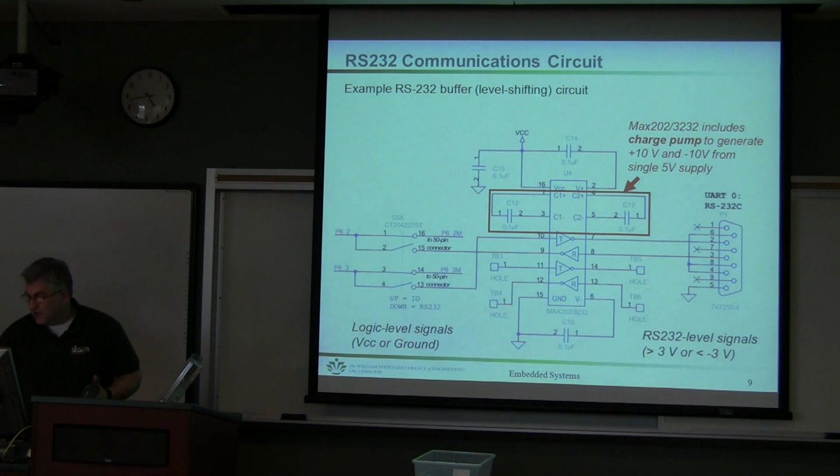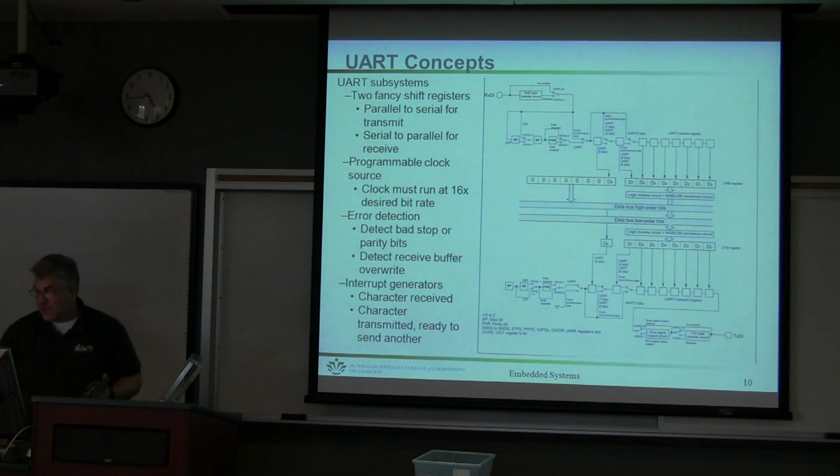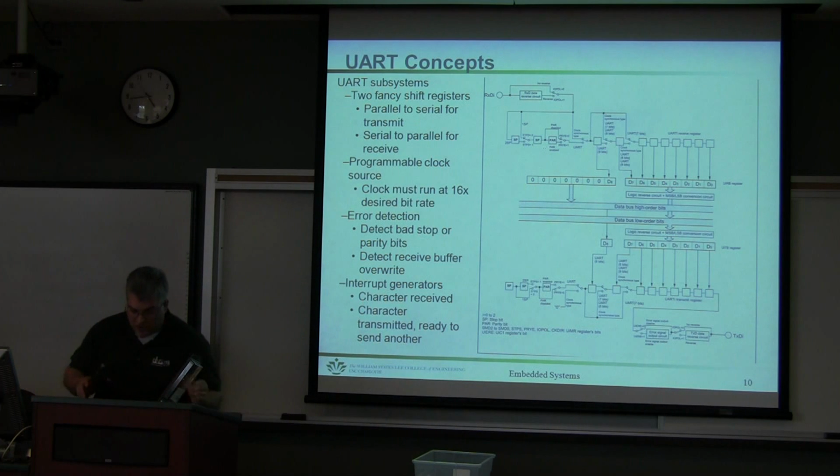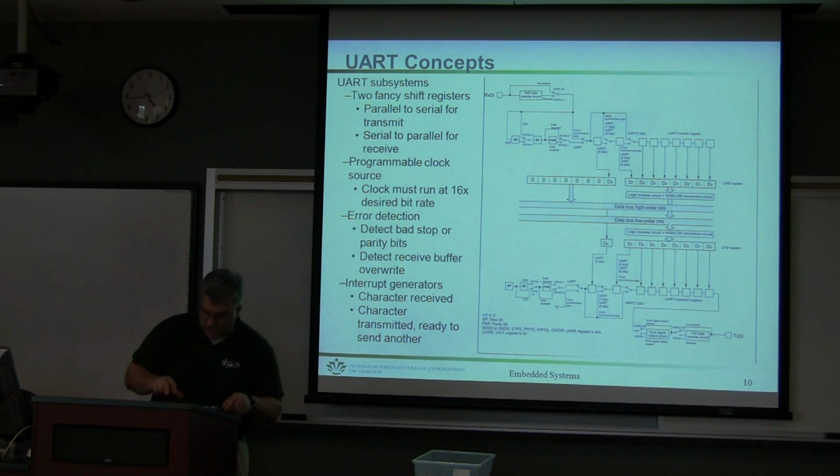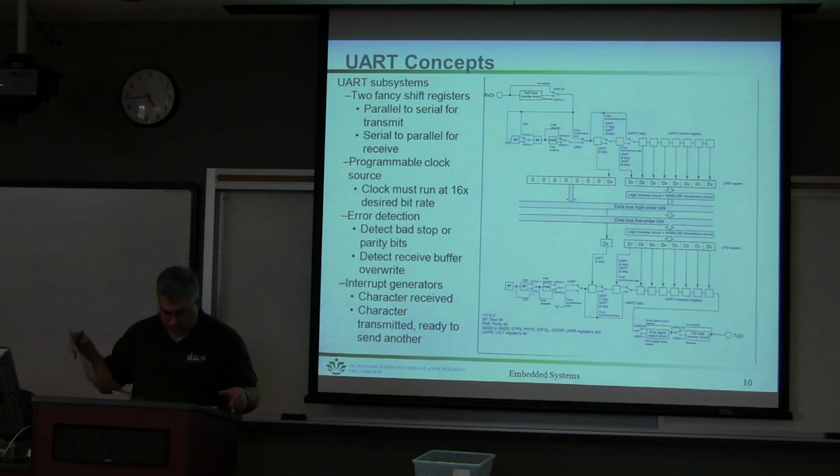By the way, this charge pump generates plus 10 volts, minus 10 volts from a single 5 volt supply in an old board. And this new board, I'm not sure how much it is. That might be a good example of something for you guys to actually measure. So I may actually add that into the lab.